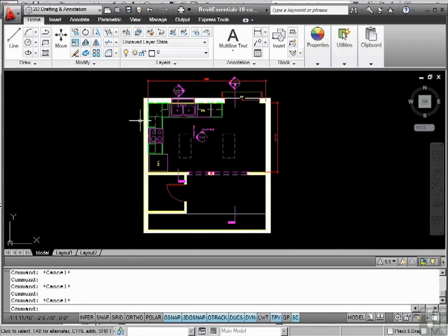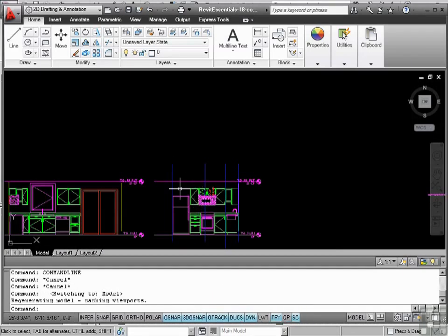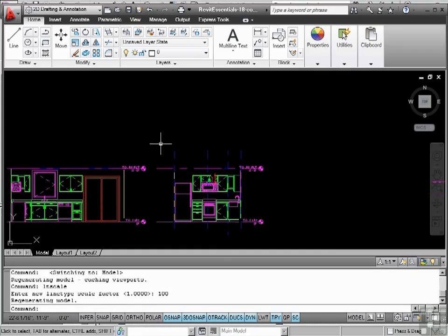You're not really going to have anyone bat an eye at your AutoCAD drawings that come out of Revit. They're going to be quite clean, and they are purely 2D. They're completely flat for the most part. Now, it exported each one of my views, and each one is equally organized. Here's another one, an example of the elevation, and you'll just find the same thing. Everything is quite organized, named properly. Hatches are right, line types are right. Change that LT scale to 100 again, just for good measure. Hatches are right, line types are right, text is right. It's really quite a clean drawing.